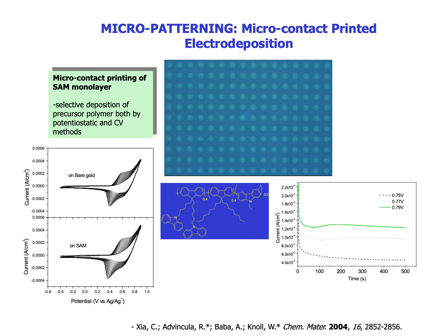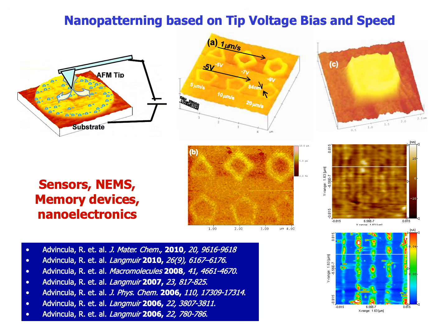In fact, this can be carried all the way to nanopatterning by utilizing the AFM tip as an electrode or a device that produces a bias voltage between, let's say, a gold coated substrate or conducting silicon. So in this case, the polymer precursor film is simply deposited by spin coating or grafting or deposition using polyelectrolyte layer by layer methods, as I'll show soon,